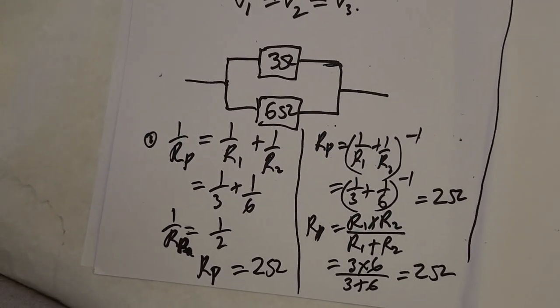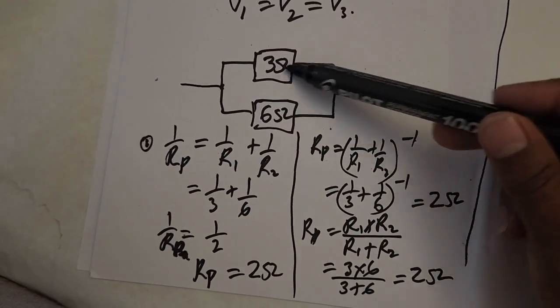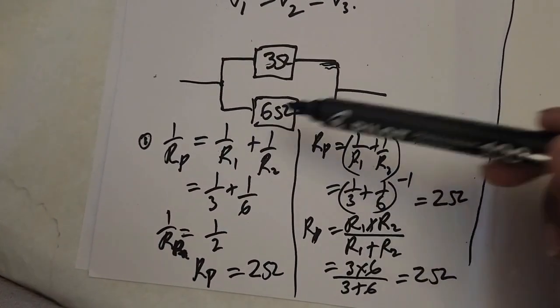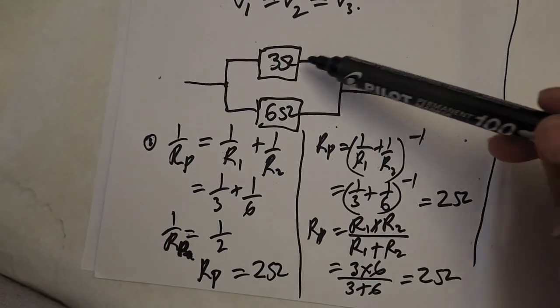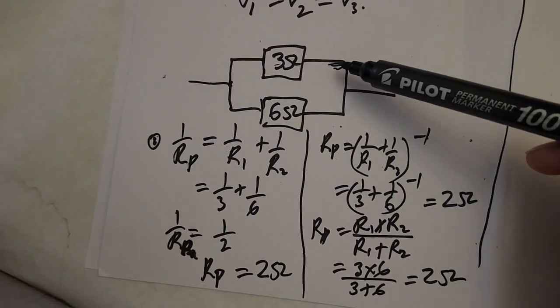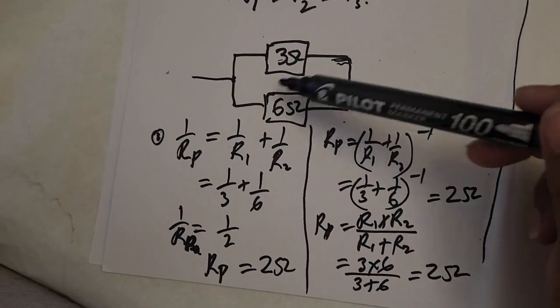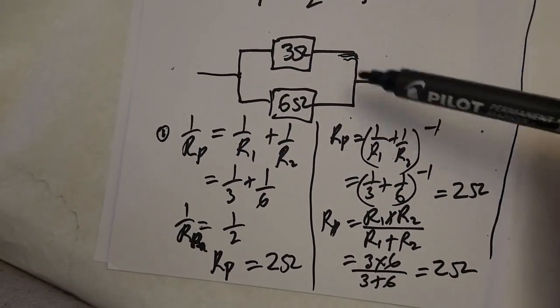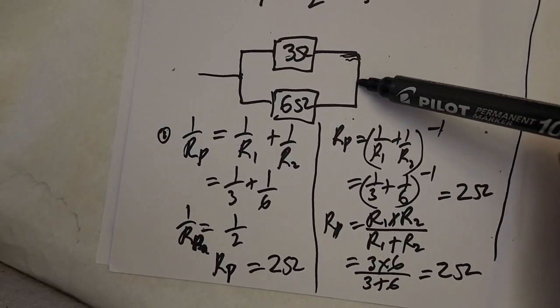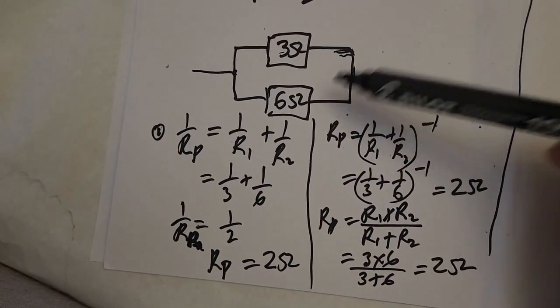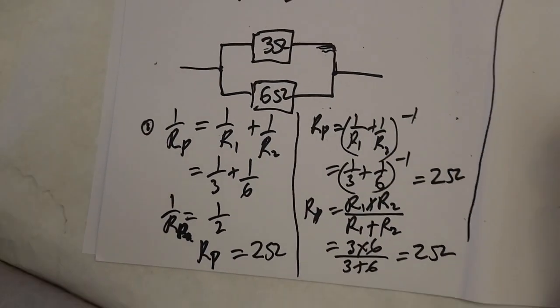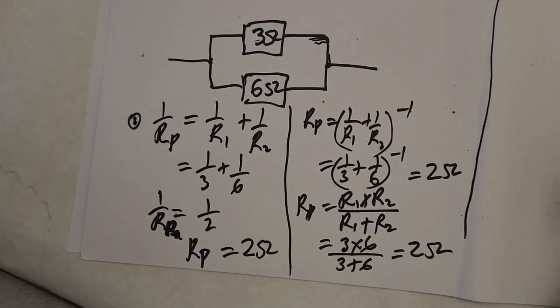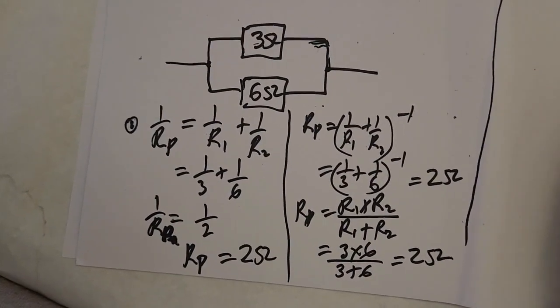Only 2 lines parallel, meaning that you can have 3 resistors in one line and 1 resistor in the other one. But know that if there are 3 resistors in here, all these resistors will be in series. Therefore, their total will be parallel to this one. So if you've got 2 also is fine. But the rule is that you must have only 2 lines parallel at a time. So that's what we will be dealing with in these questions.